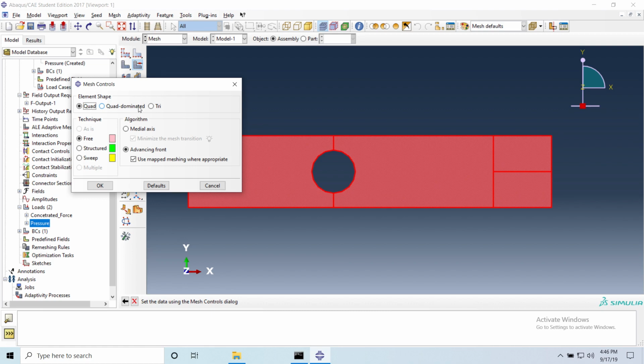Yes. So sometimes you create a beautiful mesh, you spend half an hour creating it, then you submit the job, and it says, hey, you have quadrilateral and triangular elements, Abaqus cannot compute the J integral or your energy release rate. So this is a double check to ensure that your element type is only quads. So is it ever beneficial to have the quad and the triangle mixed together? It's less computational resources, but for fracture, we can't mix elements. It has to be all quadrilateral.